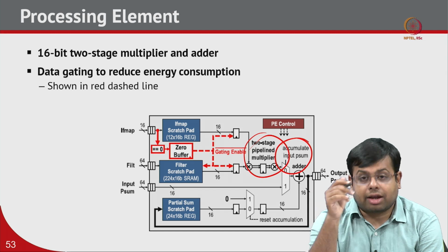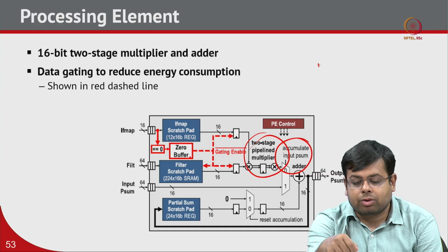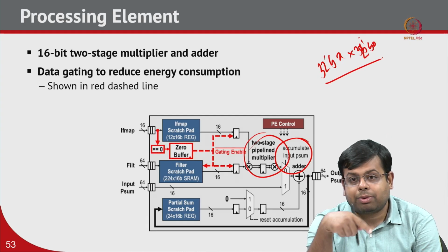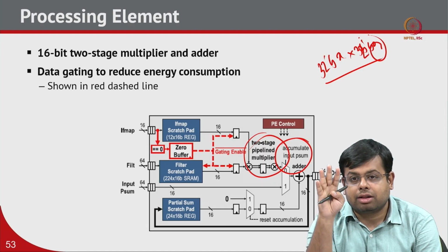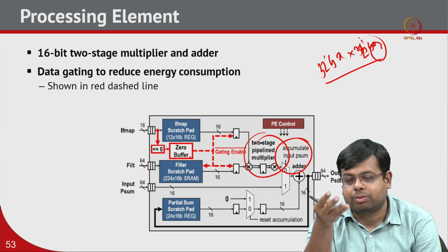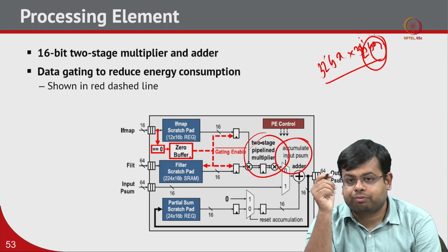If we do not do optimization and multiply a 32-bit value with a 32-bit 0, the whole multiplier circuit will be active, and it will take the same latency as a regular multiplication.